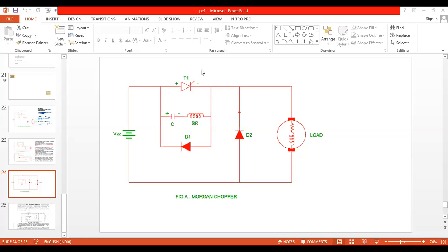After a certain period of time, when the discharging current of the capacitor is greater than the holding current, the SCR turns off. When the SCR is off, the motor rotates for a short period of time because of the inductor, as I mentioned. Okay, the same circuit. Let me take the attendance screenshot.